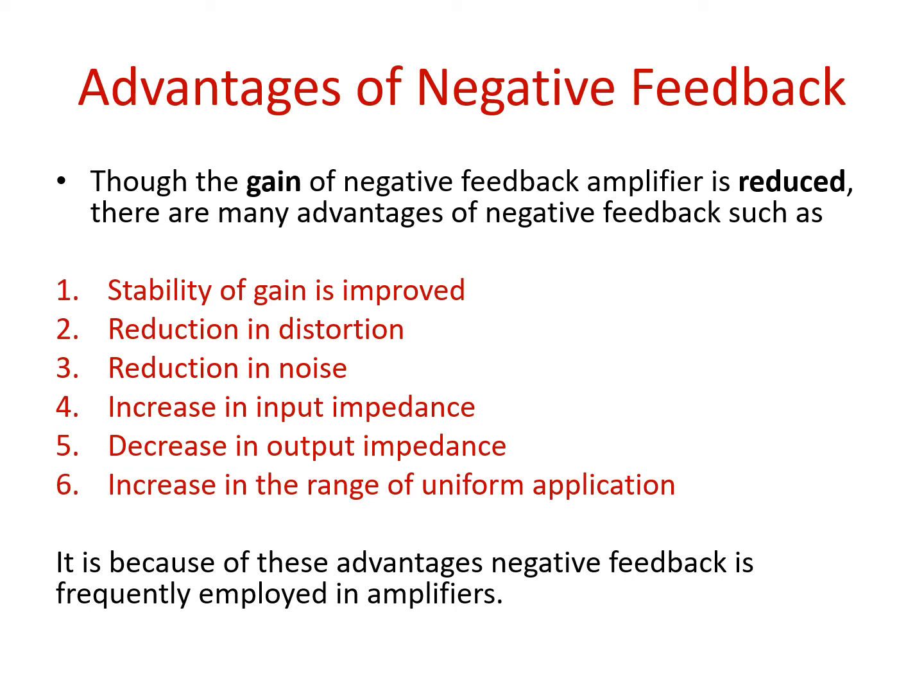Starting from number one, the first advantage of using negative feedback is that the stability of the gain is improved. Whatever gain we achieve during the amplification process while using negative feedback will be more stable as compared to positive feedback. So we'll get a stable gain throughout our amplification process.